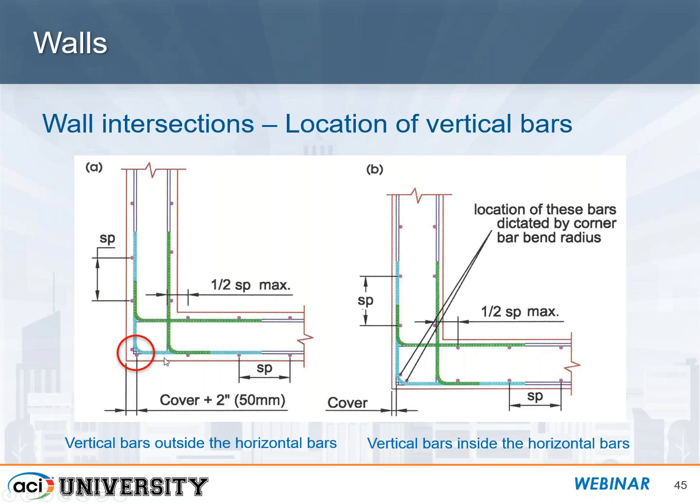Okay, and for the corner, we're going to provide 2 separate bars with a cover of about whatever you specify and another 2 inches to take into consideration tolerances. So that's a very viable solution for this particular situation. Then if you provide this, more than likely you're not going to have any issues with constructability.